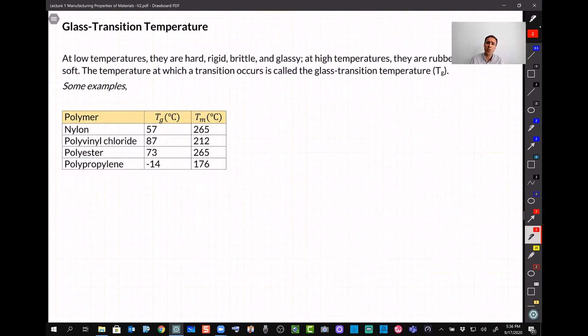Each of these materials, like these polymers, has an important property. Besides the mechanical and physical properties, they have a unique property which is called glass temperature or glass transition temperature. And what is a glass transition temperature? It is a temperature below the melting temperature, and in simple words, it's where the material or the polymer becomes soft and formable. And that's an important property when we want to make things. For example, last year, when students made their mask, they needed to calculate the Tg, or the glass transition, because you need to get the temperature of the plate to the right temperature. It has to be just right. If it is hotter or colder, you don't get the product that you want.